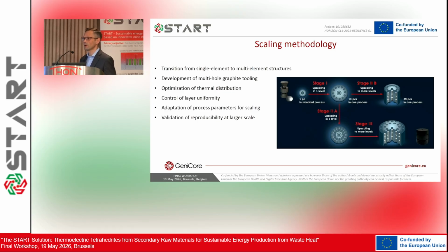The same with the load. We count, of course, the total surface of the pressing system, and if we had, for example, 50 megapascals and the load was, for example, 2 tons, we have to recalculate it and use 10 tons. Yeah, this is why it's not a completely new situation, but we can rely on the achievements from the first stage.